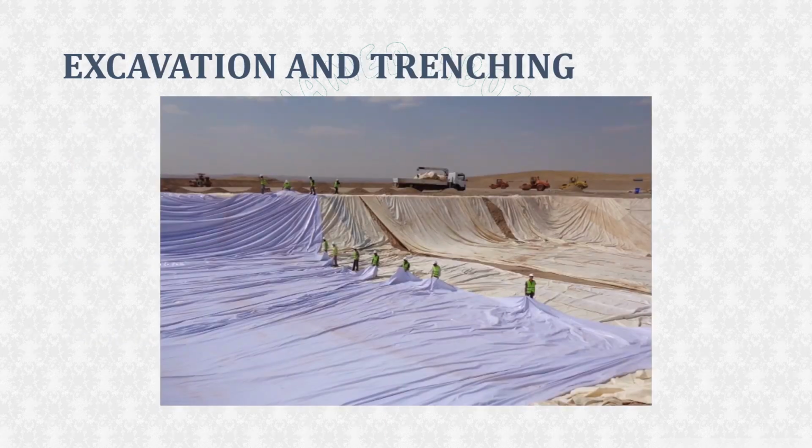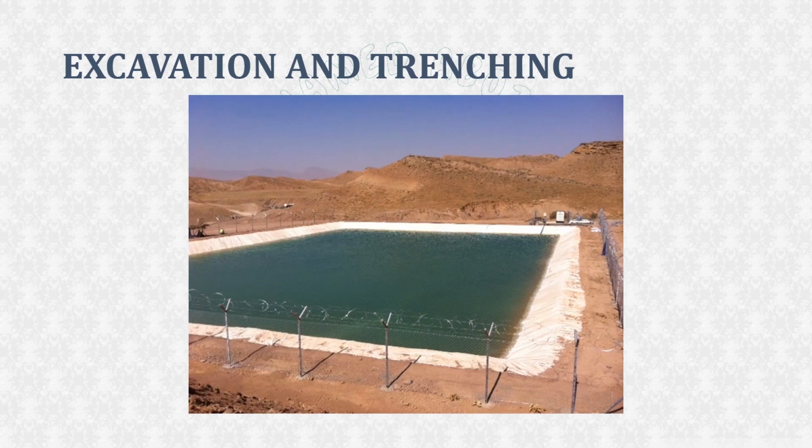The waste pit should be excavated slowly. This increases the strength of the walls and prevents the collapse of them. In some remote areas, it's hard to find an accessible water source, so we go for excavating a water bed to store water enough for the drilling operation. This water bed should be designed with enough capacity to support the drilling operation in a complete mud loss situation.